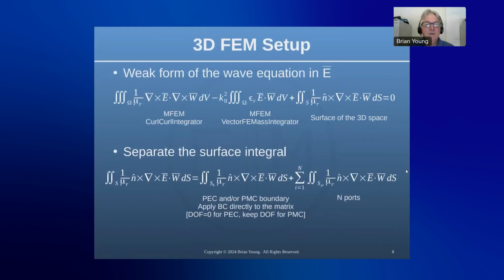So moving on to the 3D finite element setup, the simulator uses the weak form of the wave equation. So this is basically exactly what everybody else does. So there's nothing innovative here. And FEM is very well set up to solve this equation with the one exception I'll talk about, which makes it a little more interesting. So the first term can be solved with the curl-curl integrator,